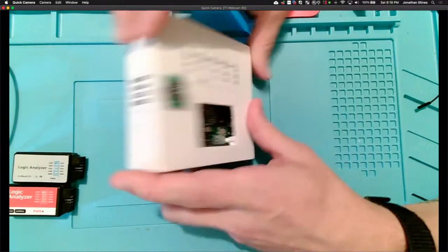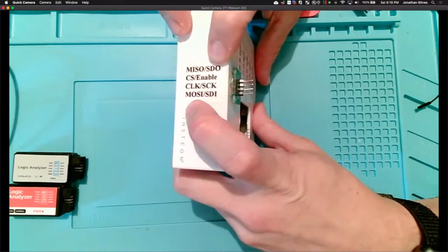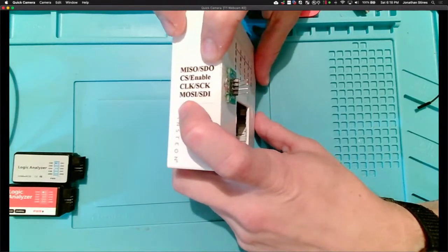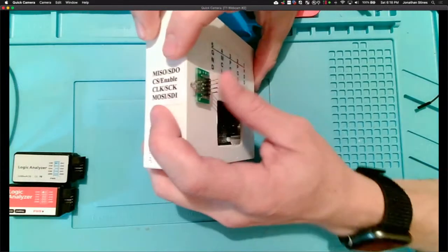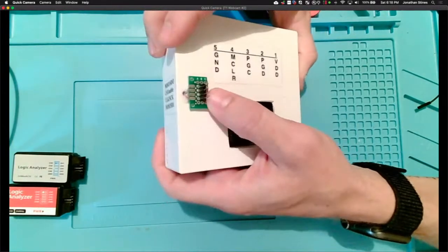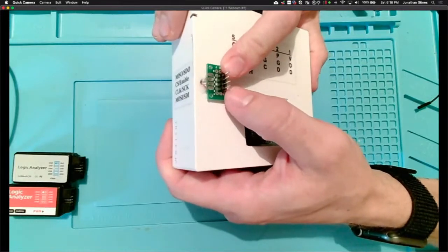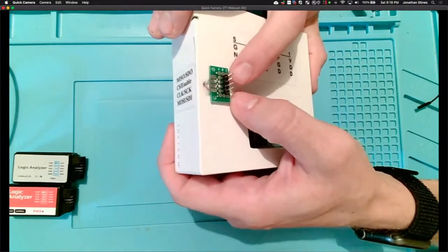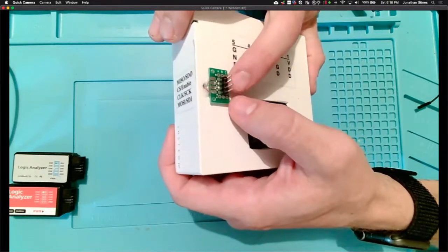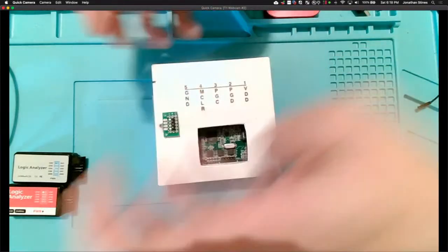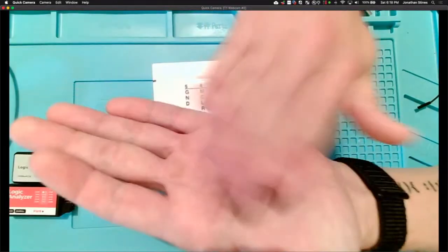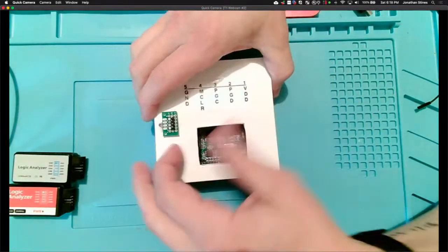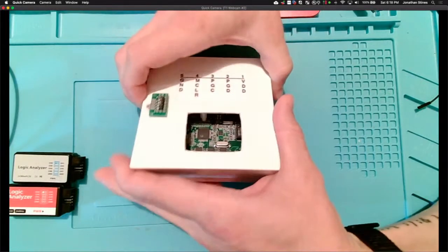Now, it's going to be an open book situation, but we're also going to pretend we don't know the pinout of this, just to make it interesting. We do know it, but I'll show you how you can make that determination, because it's so common that maybe you'll have header pins soldered onto the vias, or maybe they're only vias and you have to solder the header pins yourself, and you have no idea what they are. And maybe, for instance, you have a WSON 8. That means it doesn't have legs. All the solder points are on the bottom, like if it's BGA. So you couldn't take a multimeter to figure out the pinout, even if you found the datasheet. So kind of nifty here.